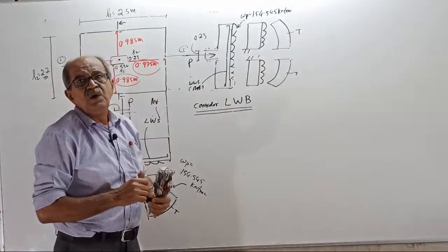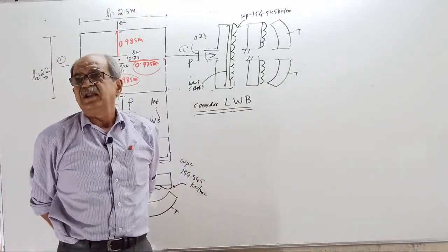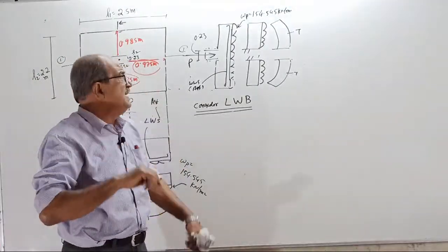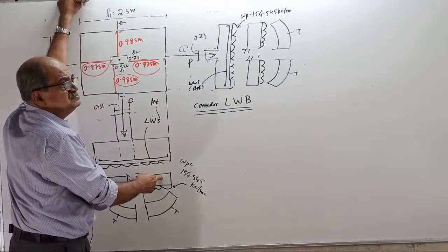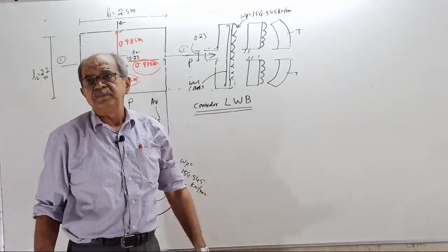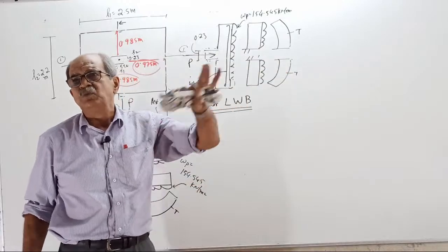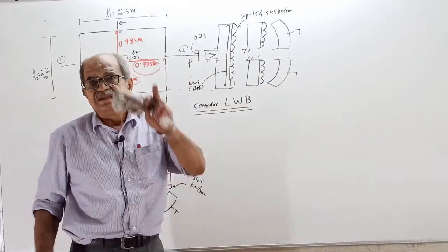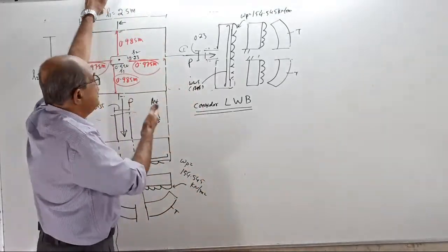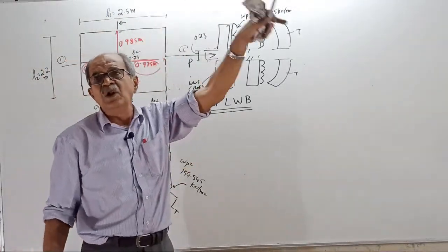But later, when you write, I'll give a separate procedure for you. But write a note. Later, when we consider axial load with M1 and M2, at that time pressure will not be uniform. It will be non-uniform. That is, instead of UDL, it will be UVL, represented by a trapezium. I will tell you at that time what to do. And practically, that is more important, P with M1, M2. This you never get practically. But then why do you require it? If this is clear, then only that will be clear.